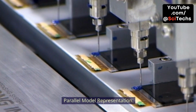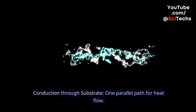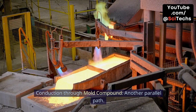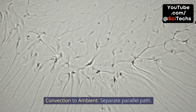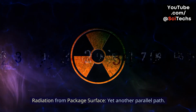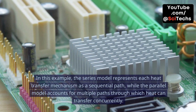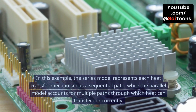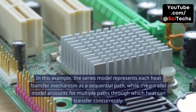Parallel model representation. Conduction through substrate, one parallel path for heat flow. Conduction through mold compound, another parallel path. Convection to ambient, separate parallel path. Radiation from package surface, yet another parallel path. In this example, the series model represents each heat transfer mechanism as a sequential path, while the parallel model accounts for multiple paths through which heat can transfer concurrently.